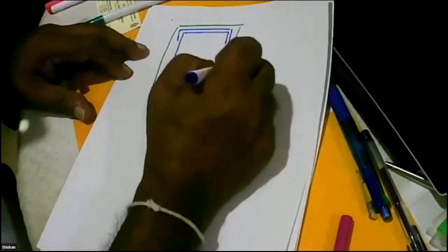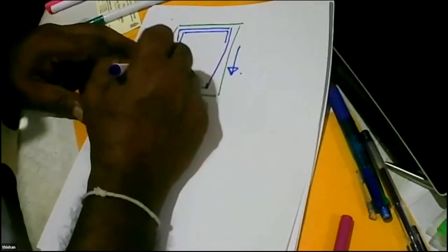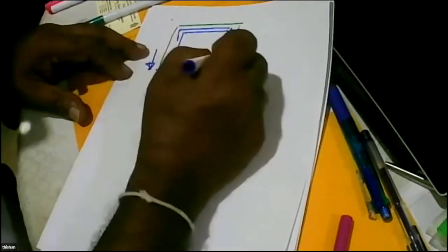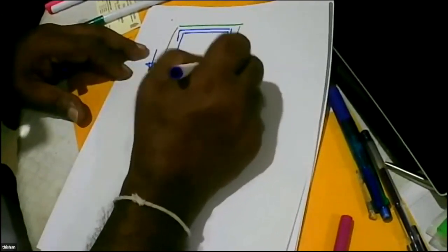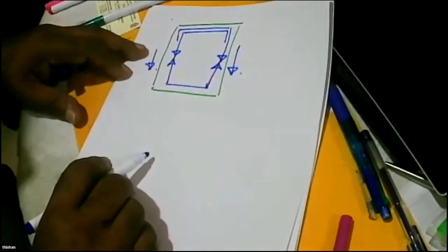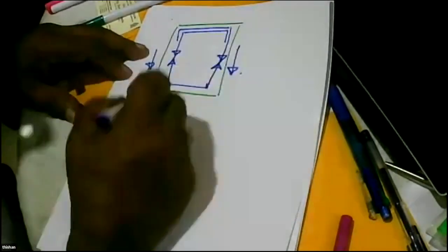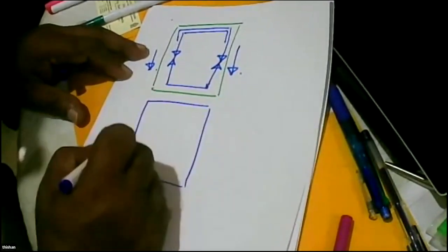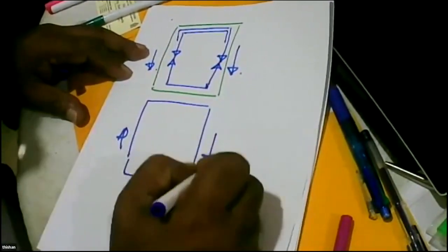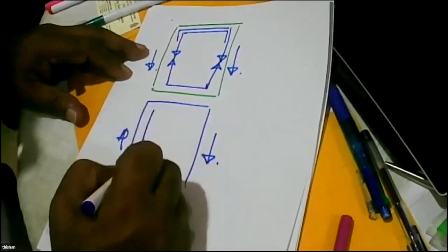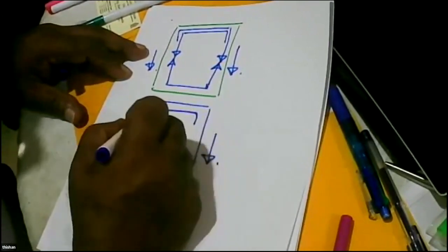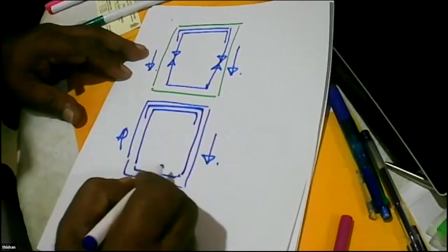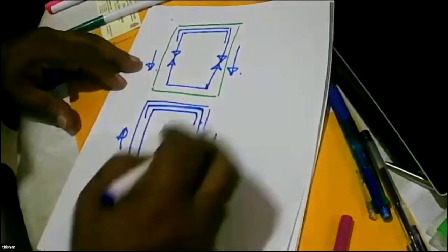When direct shear happens, this will all go into tension, so we have two legs. But torsional shear occurs differently. It is going right round, so we cannot have two legs at once. Each leg should be considered separately. That's why we consider only this leg.